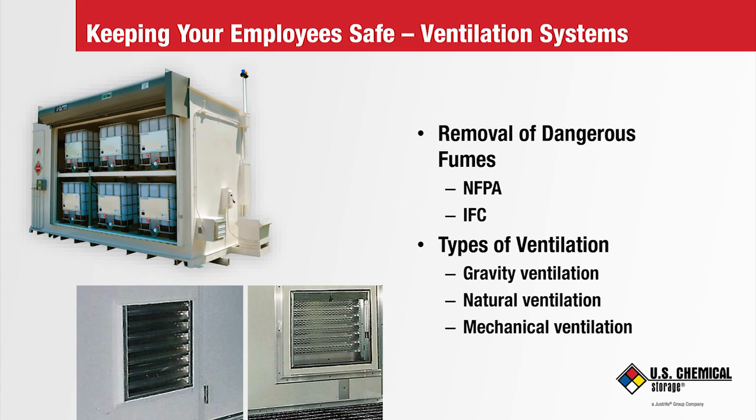The top of the rising fumes will be pulled out of the opening by gravity, like a hole in a coffee cup, allowing the fume to drift down on the ground where it eventually dissipates into the atmosphere. If there was another vent, like the first one, on the opposite wall, the wind outside the building can push fresh air in and or pull out the fumes outside. This is the least expensive and least dependable method.